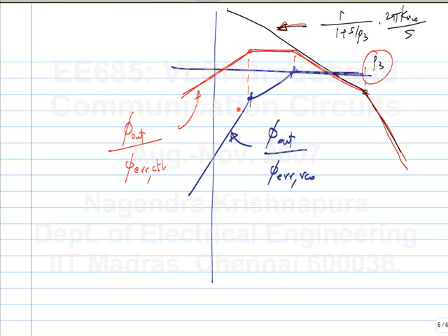Now when you use a CDR with a linear phase detector, you get similar transfer functions. Again, you evaluate the same thing. Maybe you have a noisy VCO, you calculate the effect of that on the output. Okay. And if it's very noisy, you may have to filter it. Or if the data has a lot of jitter, you may have to filter that by using a low bandwidth, etc., etc. Okay. Any questions?